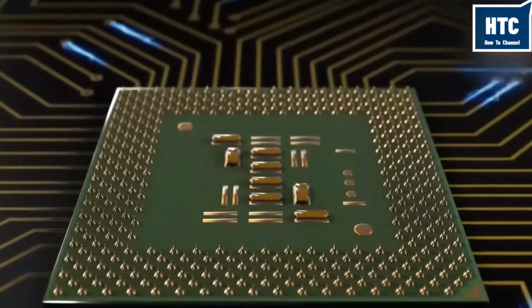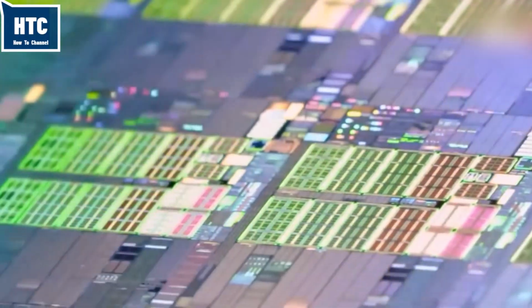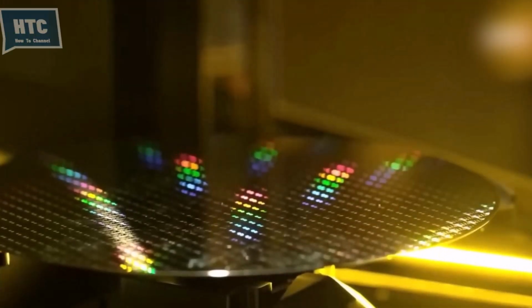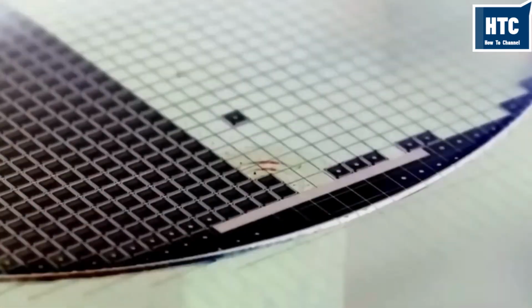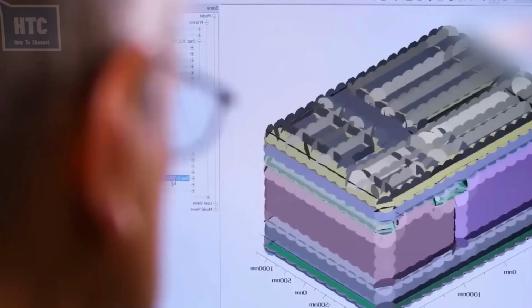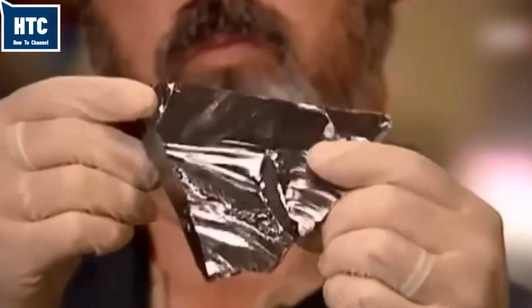But 98% purity is nowhere near enough for electronics. We need the 9 nines, 99.999999% purity. To achieve this, the silicon is crushed and reacted with hydrochloric acid to form a gas called trichlorosilane. This gas is distilled and purified, then decomposed back into solid silicon rods using the Siemens process. This is now electronic-grade silicon.